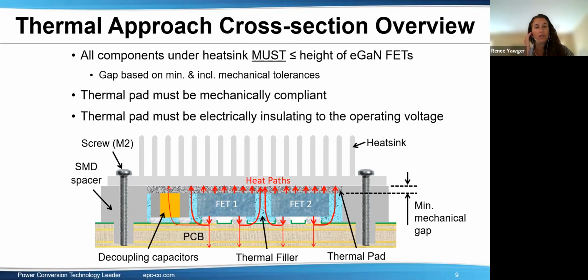In the last few years, some semiconductor vendors proposed a source down package. The idea was because a large amount of current flows under the gate, most of the heat was generated near the source terminal rather than near the drain terminal. Is this also the reason why the heatsink on the top of the EPC device is more effective?